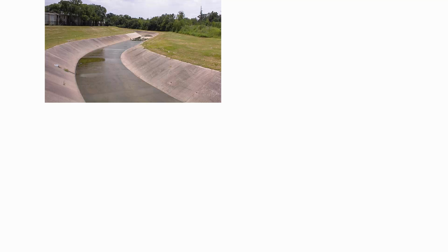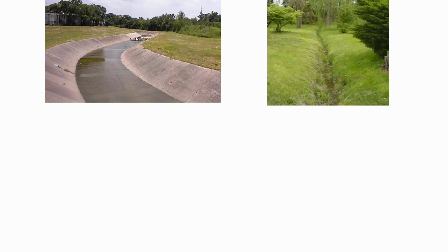Now the hydrology side of things is the calculations required to estimate what the flow rate is going to be for a certain storm. But today we're going to look at the difference between concrete-lined channels like this. This is an irrigation canal that is man-made and very smooth, likely to lose less water due to infiltration down through the soil than a grass-lined channel. Of the two, this grass-lined channel obviously costs a lot less money to put in. And which one to go for depends on more factors than just your budget.